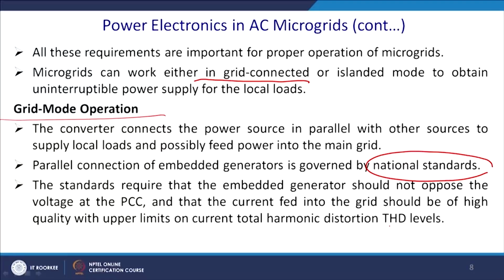When you are connecting and supplying to the grid, we have to ensure that, since you are using power electronics devices and thus have switching, you may have a problem of power quality. That does not happen when you are supplying to drives, maybe, as that is an internal problem. When you are connecting to the grid, it may affect other customers. For this reason, the power quality norms require to be maintained.